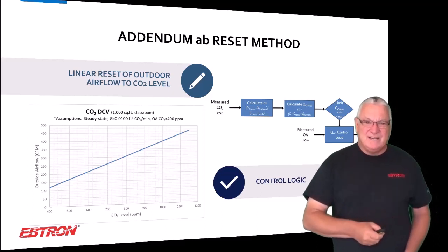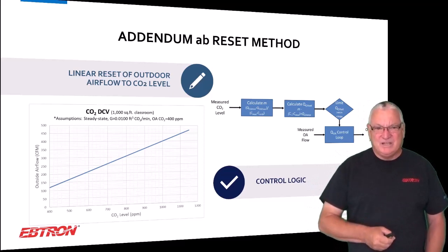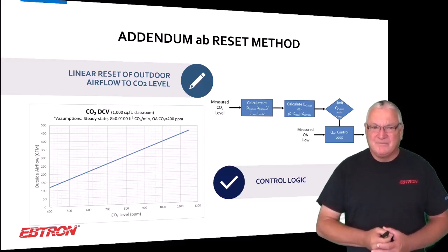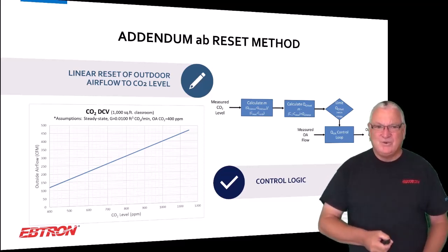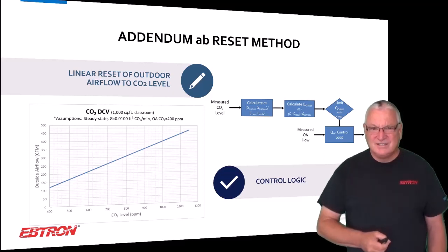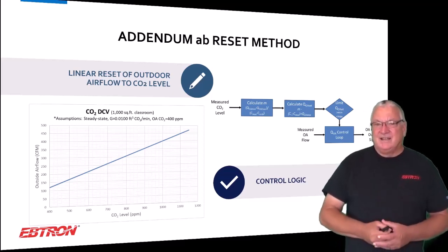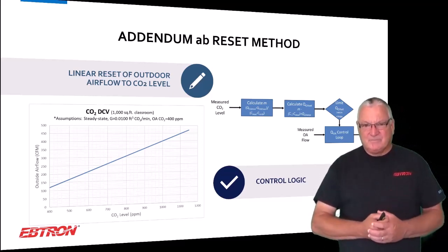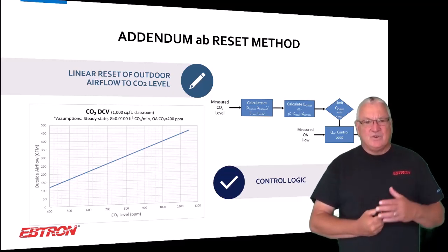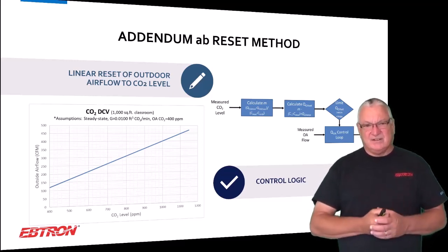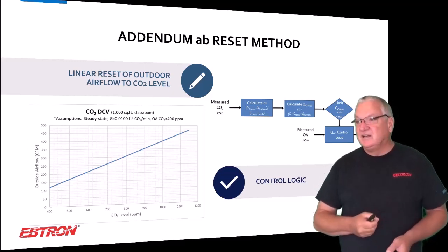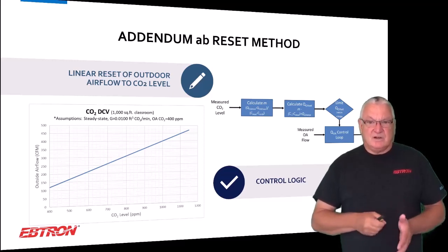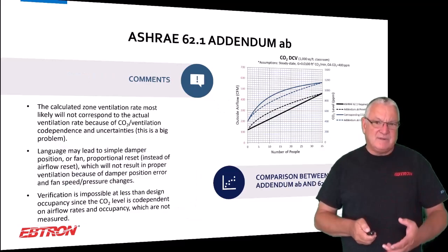The problem with the way it's written, and you kind of have to read between the lines, is that in this case the ambient is like 120 CFM of outdoor air. Well, what if you had 200, 300 CFM of local exhaust? That should be your min. So you're going to do this by putting in an airflow measurement and using this kind of strategy here to set limits. And of course, you don't want to go above the max. And the way the standard is written, you don't have to go above the max. If you can demonstrate that you have the maximum design outdoor airflow, you can be in CO2 alignment and comply with the standard. So I kind of like this method.